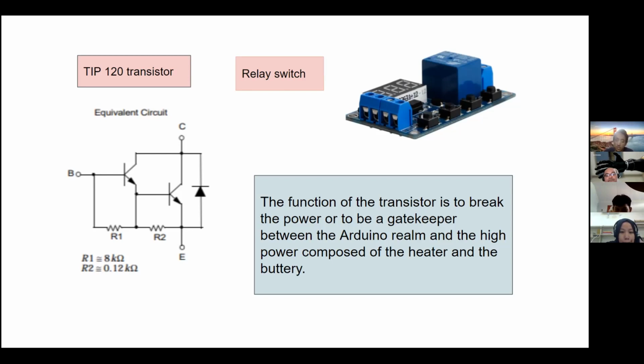The Darlington transistor is actually two bipolar transistors connected in such a way that the current amplified by the first transistor is amplified even further by the second transistor. This model offers higher common emitter current gain than if we use separate transistors, and can even take up less space because both transistors can share one collector.